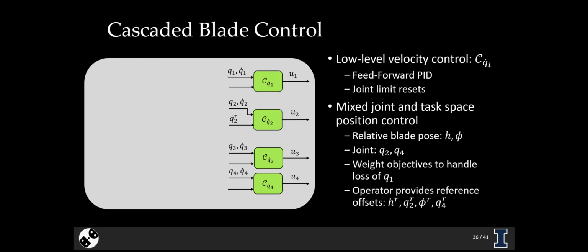What you're doing when you're sending these control commands out is you're changing the position of a hydraulic valve, which is changing the flow to the hydraulic actuators, which then changes the extension rate of the joints. So it's pretty proportional to the actual velocity. And we additionally made some modifications to deal with the fact that these systems have pretty intense joint limits. So it's a very, very small range of movements of some of these joints. And this ends up being important, especially if you want to add things like integral control, so that when you're backing off of these joints, you're not lagging much.